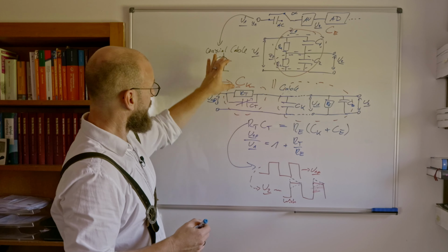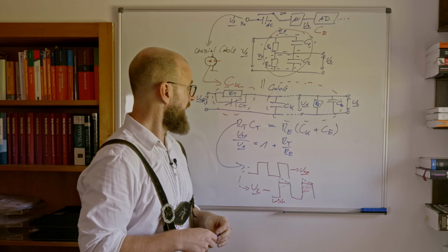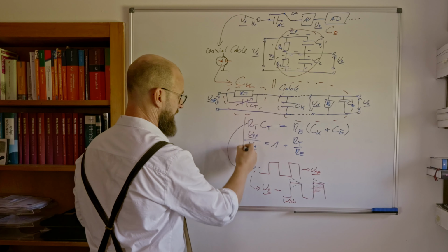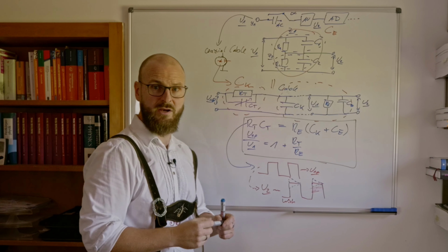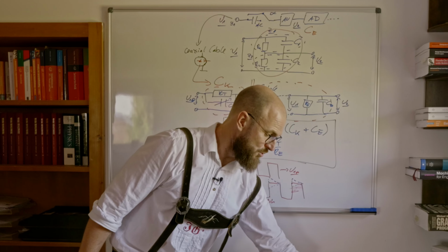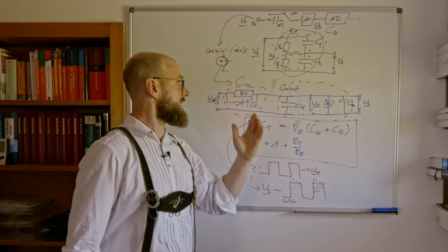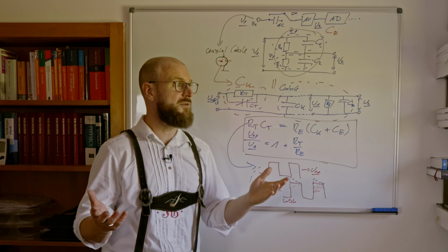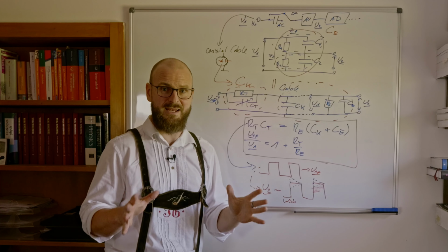Okay, that's important stuff about connection and using oscilloscopes. And those are the most important calculations, because that's the stuff you have to deal with when doing real measurements. You cannot just neglect that your system has capacitances, and those capacitances give you a frequency dependence. You cannot neglect that fact.